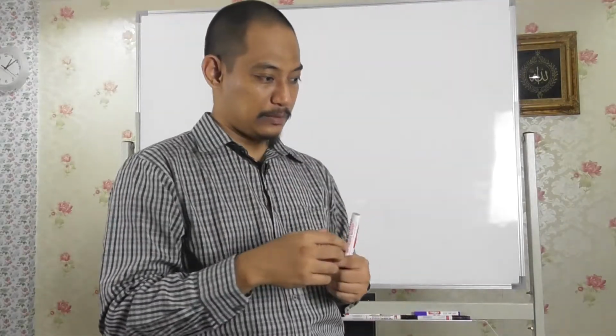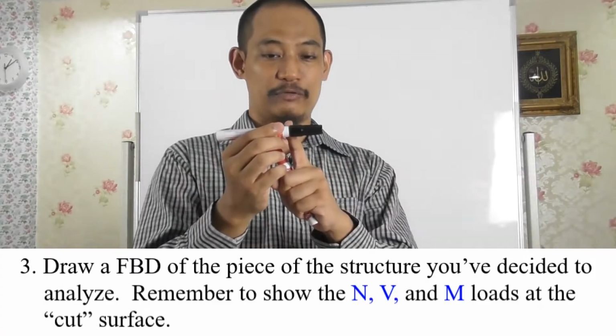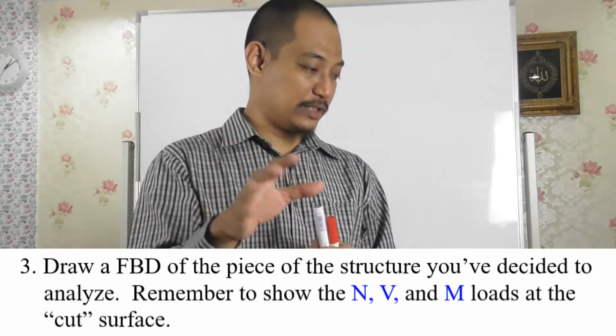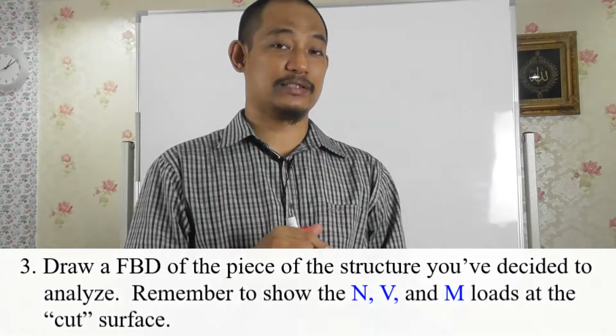So that's number 2. Number 3, draw a free body diagram of the piece of the structure you decide to analyze. As mentioned, you have two options when you have cut it, either one side or the other side. So draw the free body diagram of whichever side you choose. Remember to show the N, V and M loads at the cut surface.